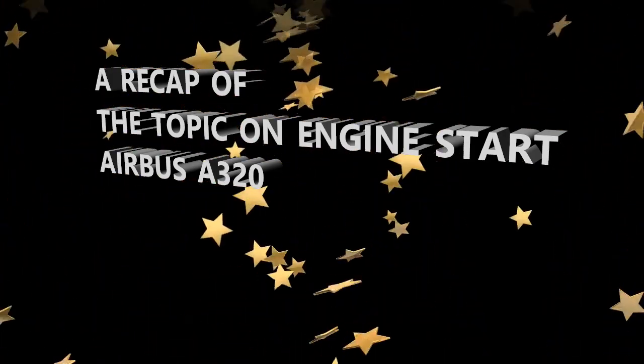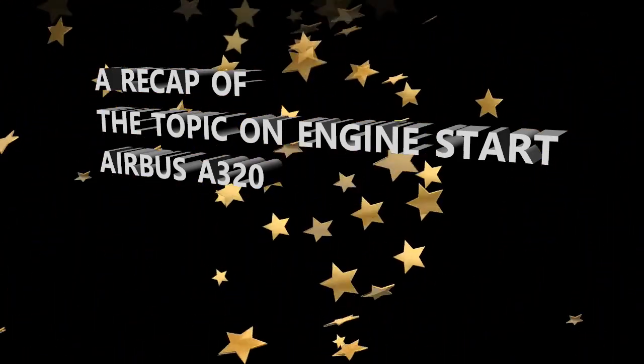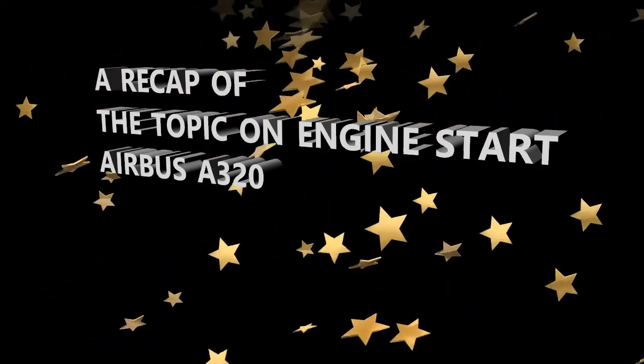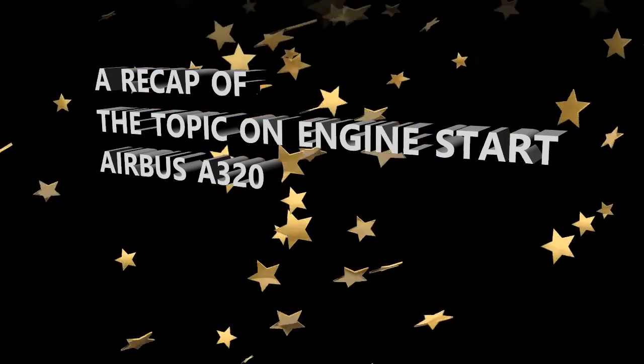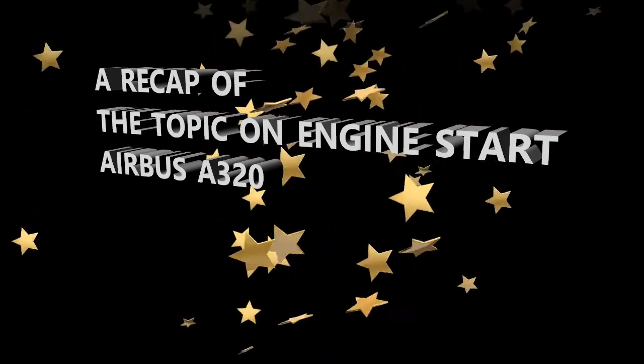We also talked about some of the failures that can occur with starting. Ignition fault, of course, your hung start, hot start. You can have an engine stall, when the compressor rotor's not up to speed, not going at the right RPMs.